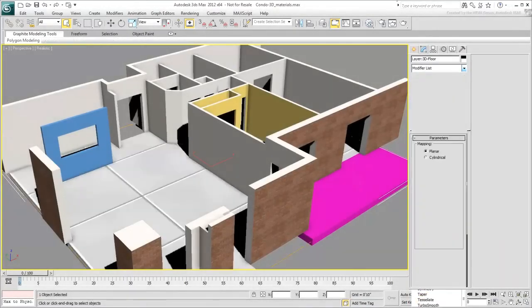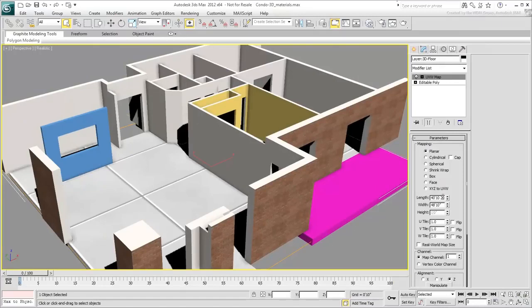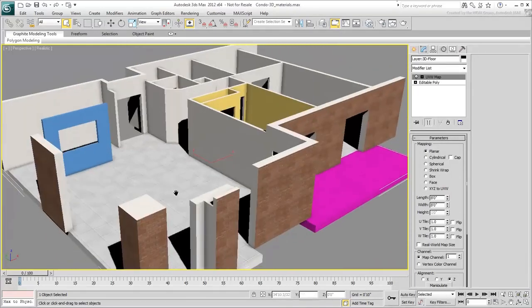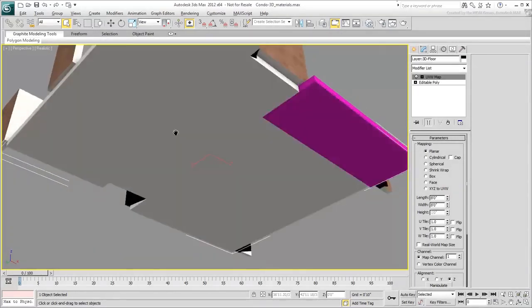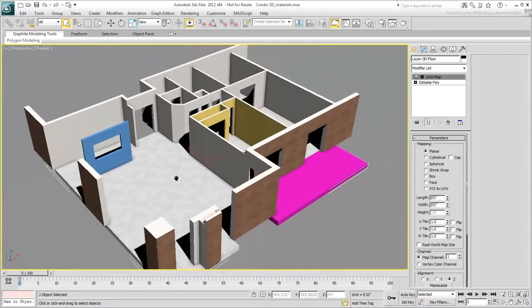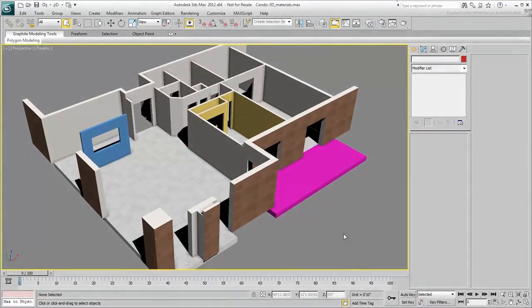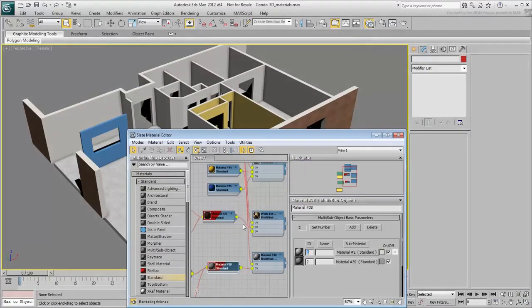If you want to have different floor surfacing, then you'd need to subdivide the surface like you did with the exterior walls earlier. This way you can define more face IDs and more submaterials. If you have time, add and apply a standard material based on a cement bitmap for the balcony slab.